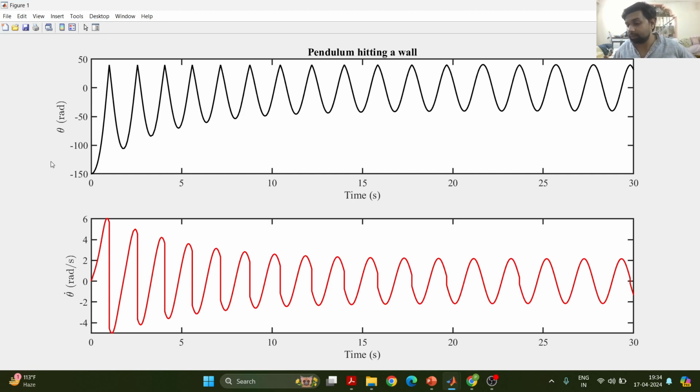So we can keep track of the angle that the pendulum has reached, and the instant at which the pendulum will reach that angle. We keep track of that, and then we stop the solver at that time instant and record the solution from the initial conditions at which we had started up to the next collision event.